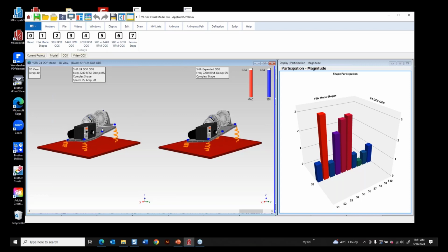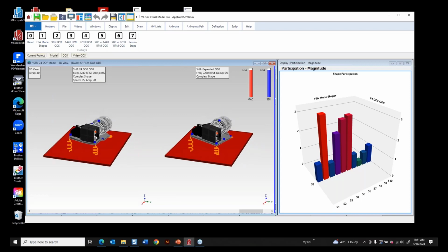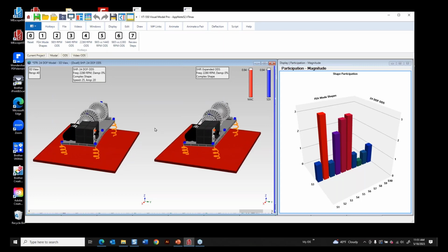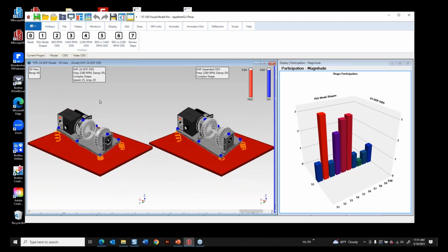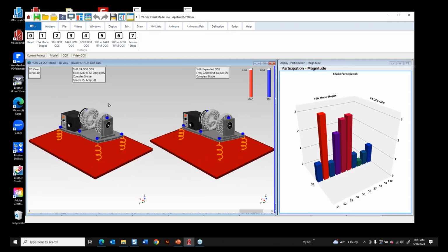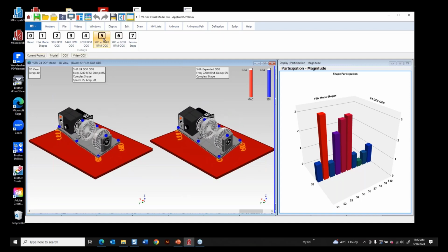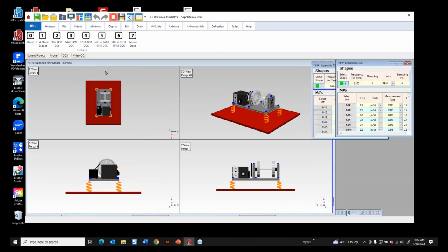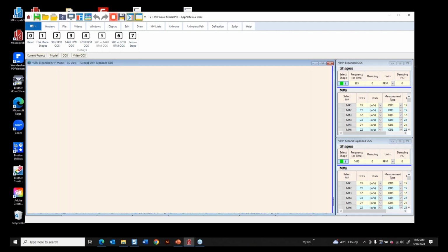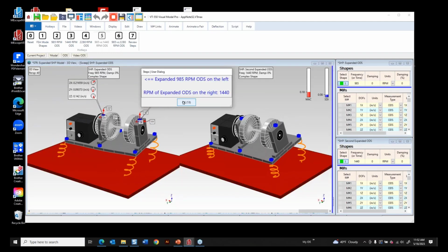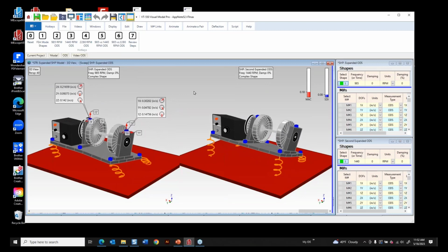But you can see the real data. These accelerometers were just stuck on with magnets. You can see kind of a wild point here, but the curve fitting over here gave us a nice smooth motion for that point. Let's put some magnitudes and phases up here for the bearing blocks. Well, let me show you these real quick, and then we'll go back and look at magnitude and phase, because this curve fitting does a very good job.